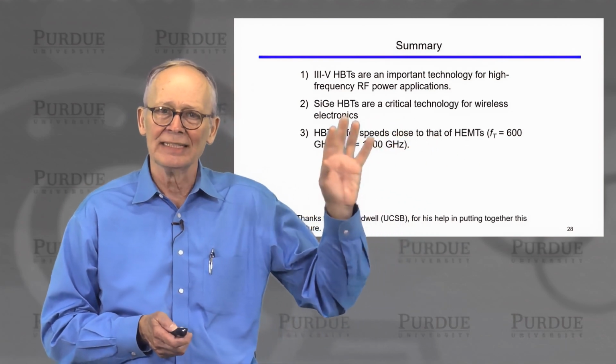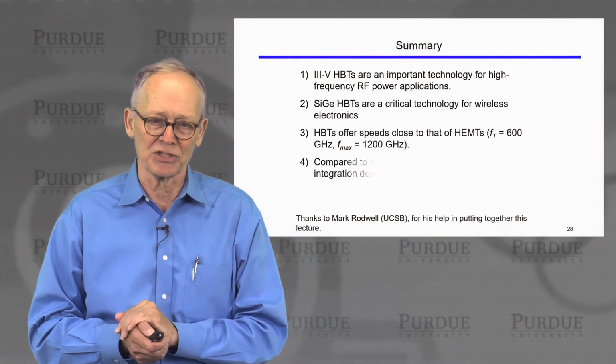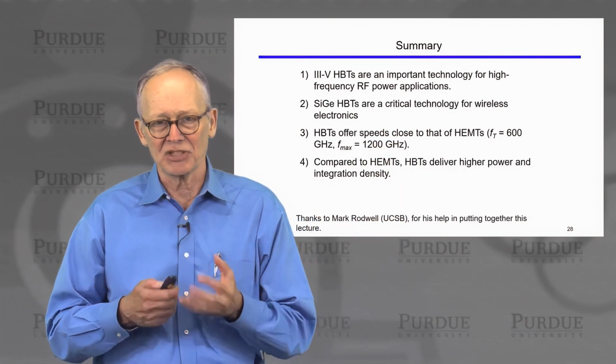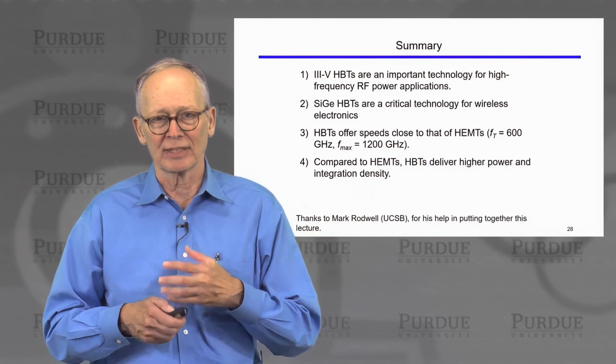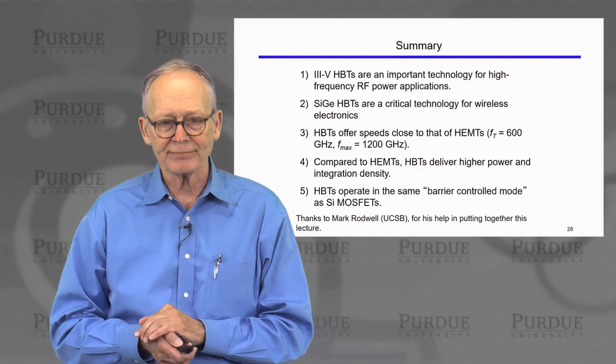HBTs and HEMTs offer similar maximum frequencies of operation in the terahertz regime these days, but compared to HEMTs, HBTs have much higher transconductance and therefore can deliver higher power to those applications where we need it.